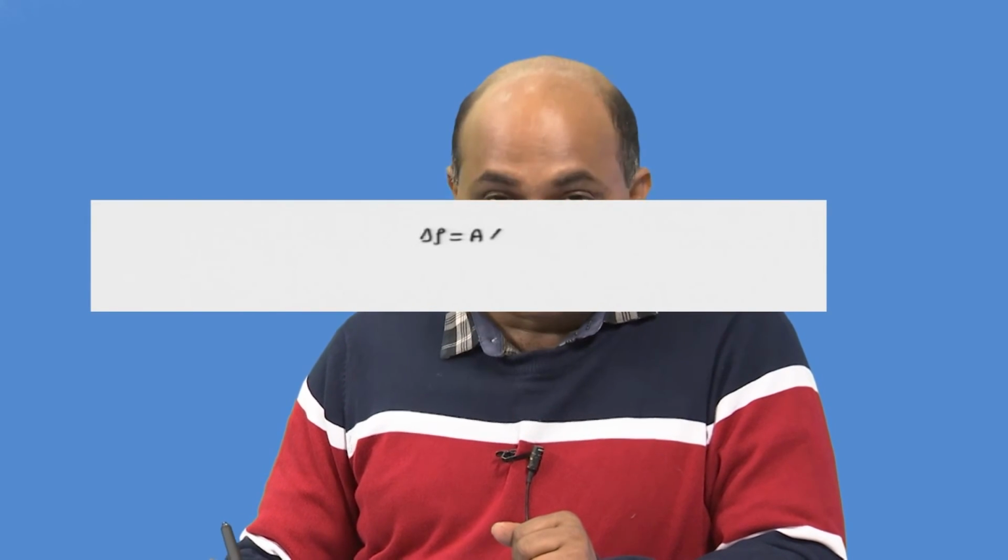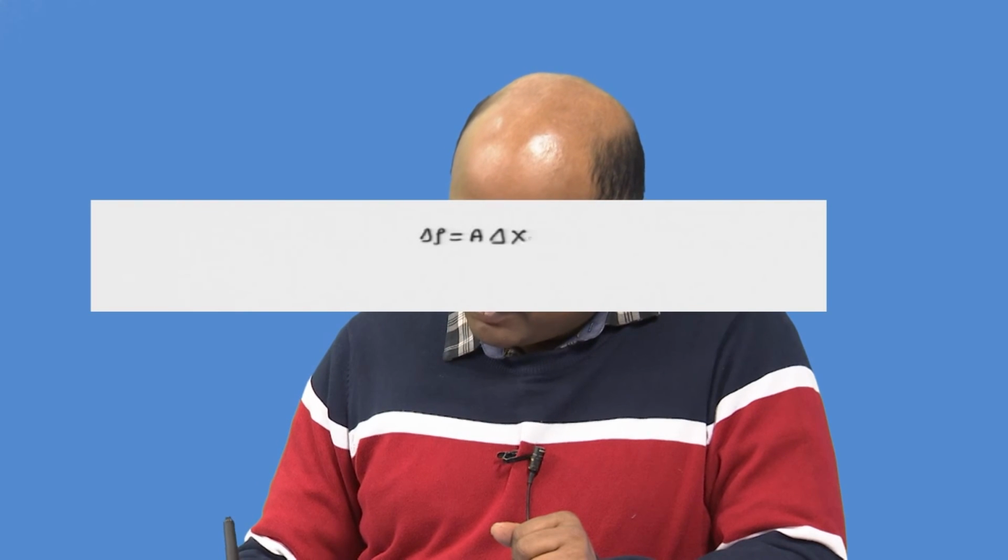Now, if the density of dislocations and the grain boundary area remain constant, the only contribution to the change in resistivity is going to be from the change in vacancy concentration, because we are doing the measurements at the same temperature, so rho T is also the same, and then we can write delta rho equal to some constant A times delta x 1 V.